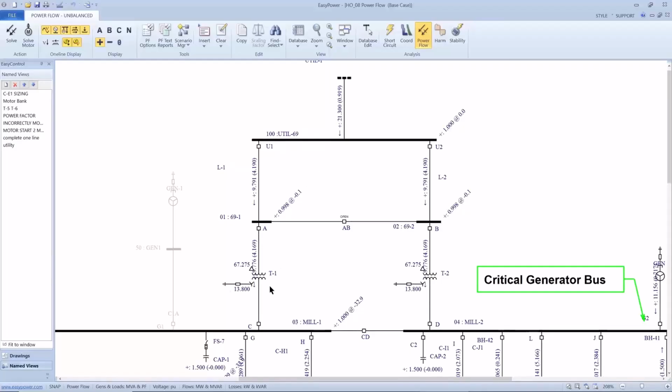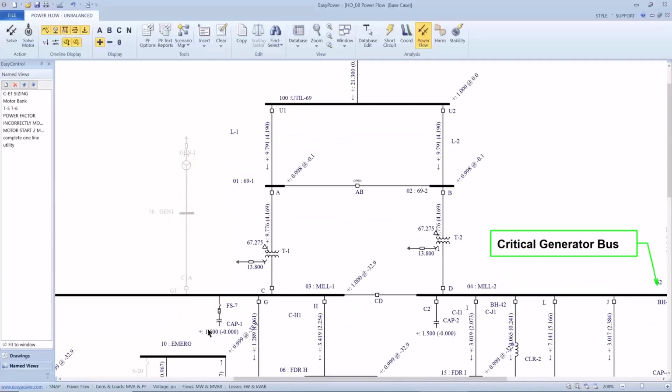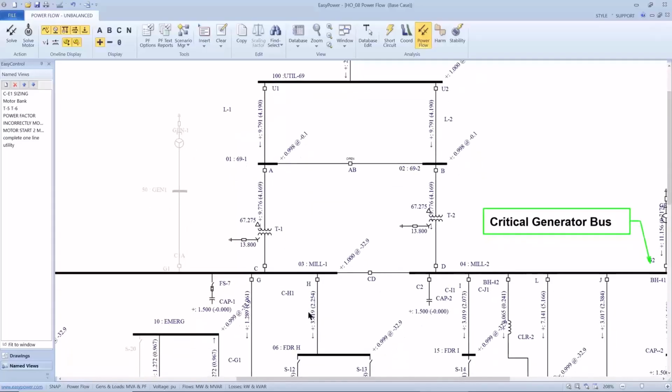And what we see as we exercise these is that the upstream reactive current changes a little bit. In this case, it's 4.865 or 855 megavar, and it drops by 500 kilovar. And what it's doing is offsetting that much reactive current into these loads that are on the same bus.